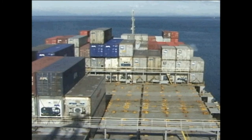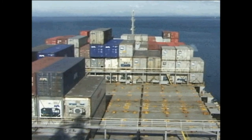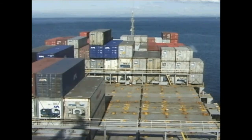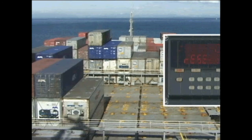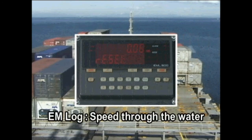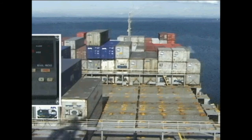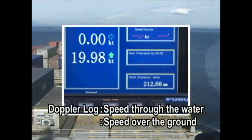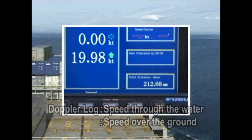Both the electromagnetic EM log and the Doppler log are used to measure ship speed. While the EM log measures only the speeds through the water, the Doppler log can measure speeds both through the water and over the ground.